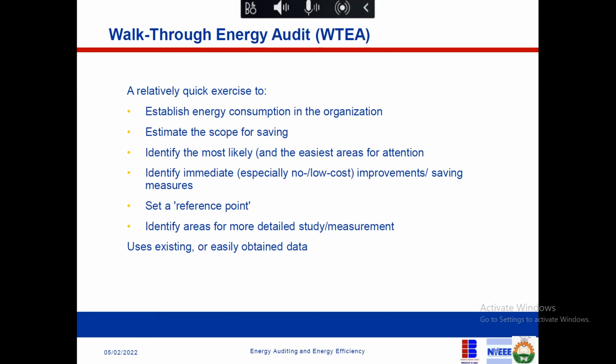So what you now do is you identify areas that need it. For instance, one of the audits I did for a hotel, funny enough, they don't have an elevated tank. I don't know how they did it. Let me not say how foolish that arrangement can be. There's no elevated tank, so water is not being supplied to the rooms by gravity. It is by a pneumatic pump system. So anytime a consumer opens a tap, the pump comes on. And so you see the pump running, a 2 kilowatt pump running 24 hours. Man, it was terrible. But that's by the way.